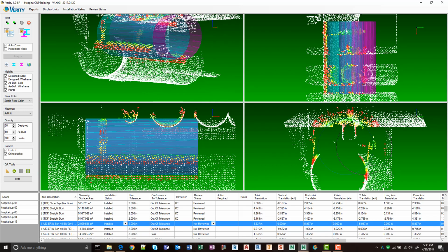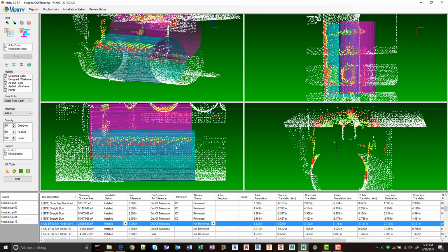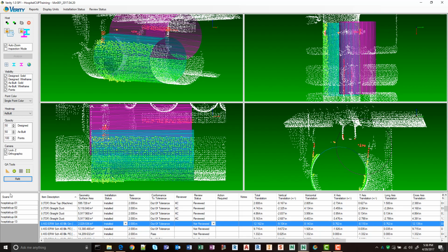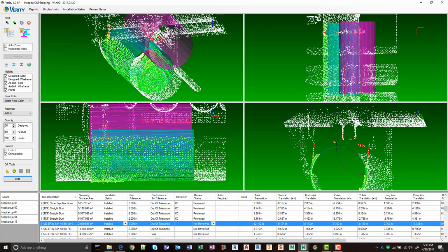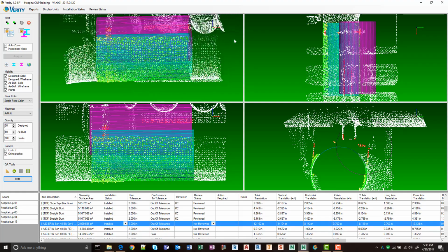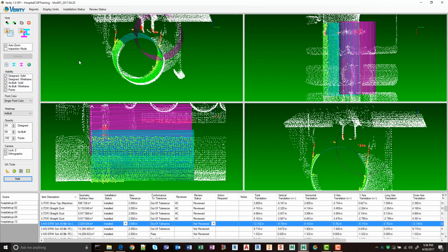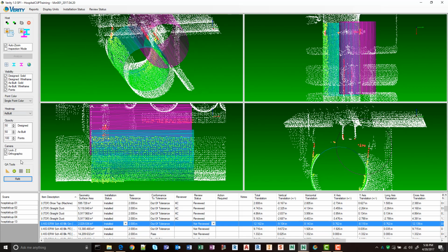However, in this case, the model data and the scan data are very similar. So unlike the others where you have to be pretty precise, drag it into a location because that's going to be your final measurement, here you can just get it pretty close and hit the refit button. And that refit button is going to use the same algorithms that we use to fit the geometry automatically, but based on your user input, so that it picks the location that you pick. And so now you can see we've got a very good fit there,